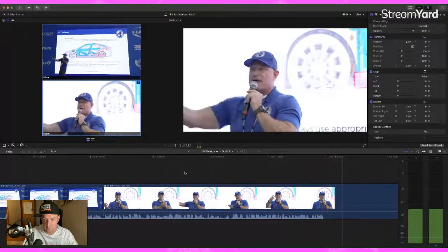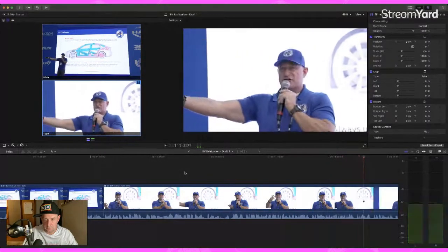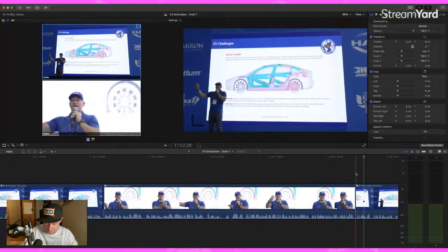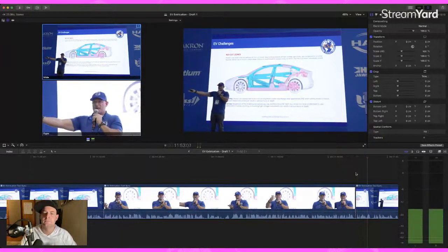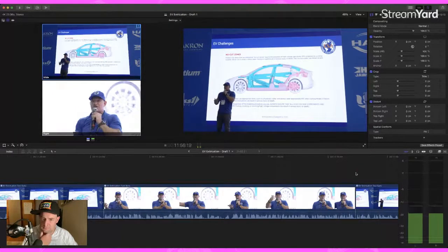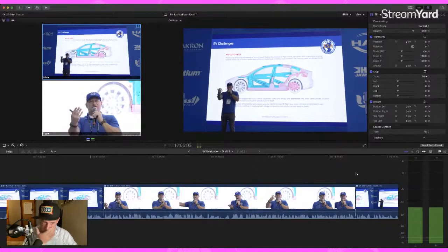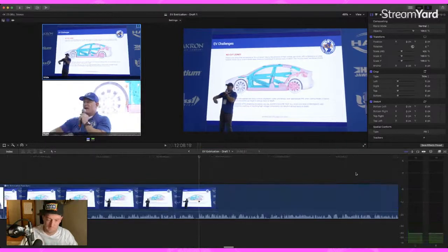Let's talk about mechanical or physical damage. That's your collisions, right? Or any penetrations to the case, any tweakings of the battery closures. Also, physical contact and damage to the components. When we're looking at this as a circuit, understand there's safety systems in here that are designed to open that circuit in times of collision.